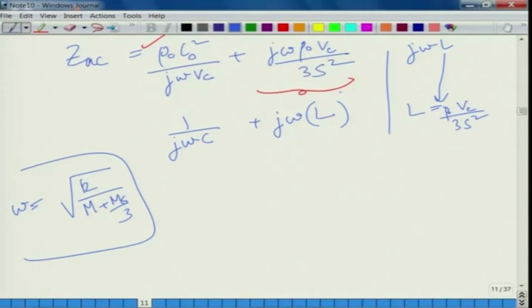But physically what it also means is that the short end cavity, if it is not all that short, has two things acting in parallel. This has a form of j omega L, this is j omega C. So this inertance term is present when you consider a correction term. This inertance acts like a correction to the compliance, which is a more fundamental behavior of such a short end cavity, and in a way both your compliance and inertance are operative, and they act in series.